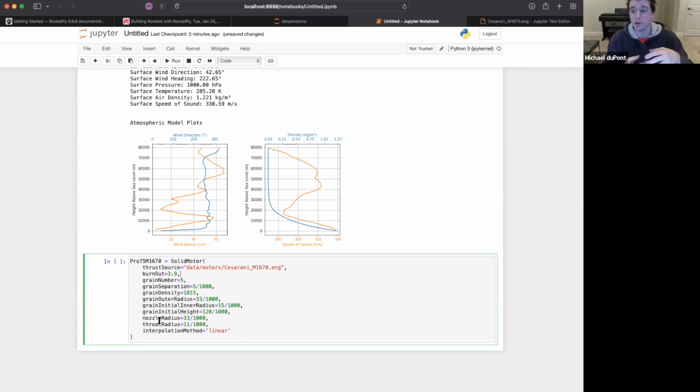Well, if this were a really large engine, nozzle radius would be the bottom of the bell, and the throat radius would be the top. In theory, kind of like think of the book and movie Rocket Boys, that sort of thing. And we can actually play with this later to optimize, say, what the nozzle radius should be. I think that would be fun to look at.